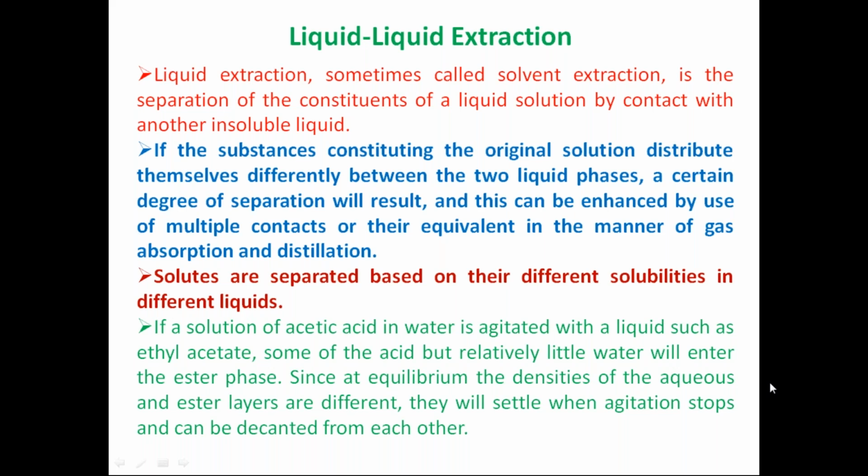So therefore, in certain cases, the liquid extraction will replace the conventional distillation operation to reduce the consumption of the energy requirements as well as other fixed costs and operating costs. Since there is an equilibrium between the two different dense phases, you can say that this is very easy to separate. In certain cases, all of you know that the density difference may be very close, and we'll see whether such types of solvents are selected or not.